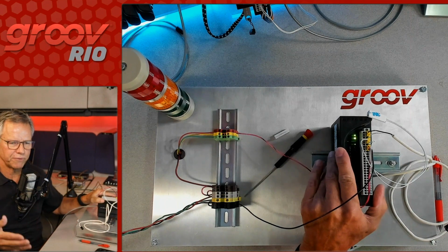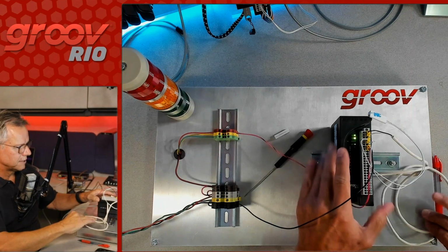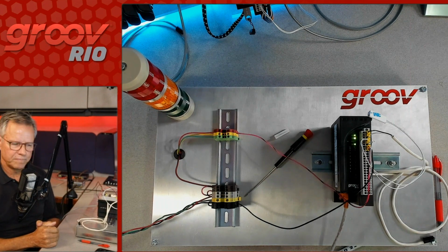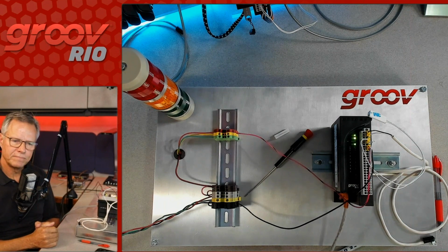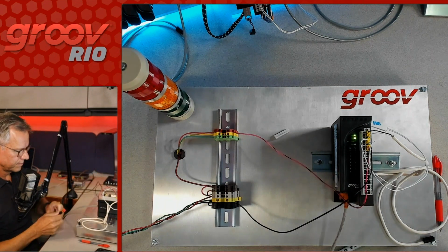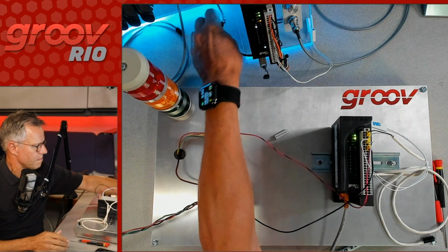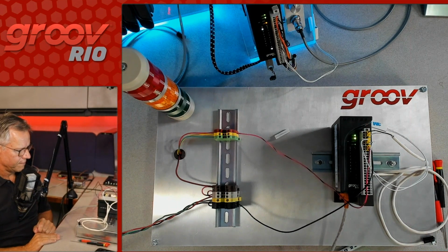So it can be different for, like Doug's using thermocouples and a humidity sensor. I happen to be using RTD and door sensors, but we're using the exact same product. Right. Another really good feature that we haven't mentioned on the Rio is it does actually have a USB port, and the USB port can be used for memory sticks, USB memory sticks, Wi-Fi adapters, and of course also, interestingly, you can configure a USB to serial adapter, and then Node-RED can run on the Rio and can actually read Modbus RTU data through that serial adapter.